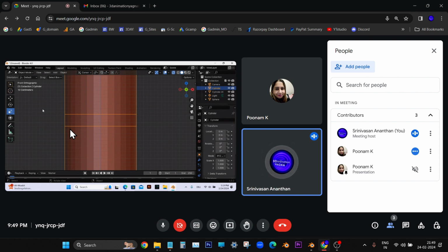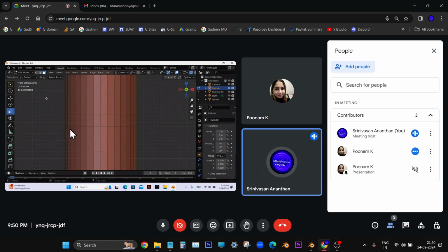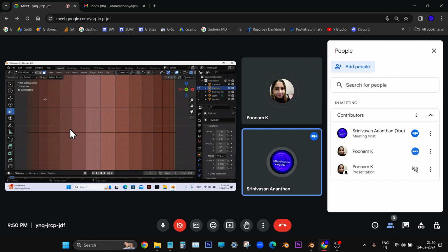Now though we have joined, it is not joined geometrically, it is still a separate object only. I will tell you how you can see it. Go to edit mode. Now zoom in carefully, zoom inside, little more, further, enough. Now switch to vertex mode. Just pick any vertex in that joint area and move it.